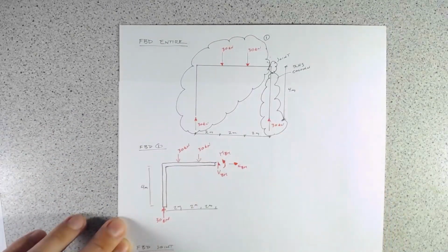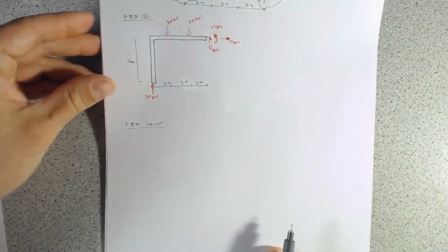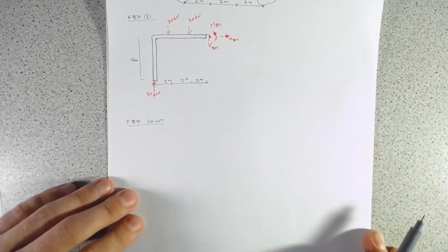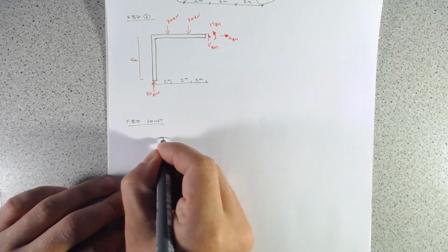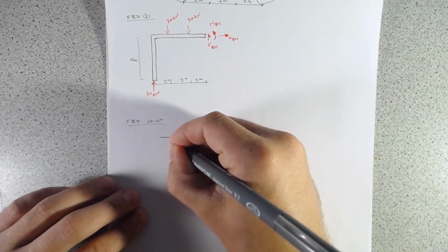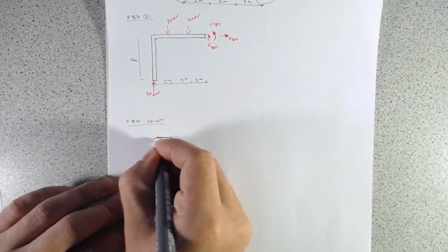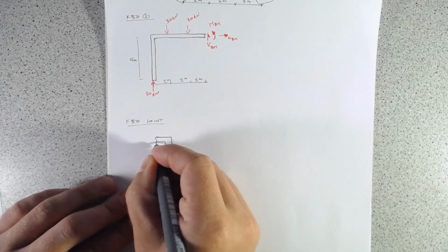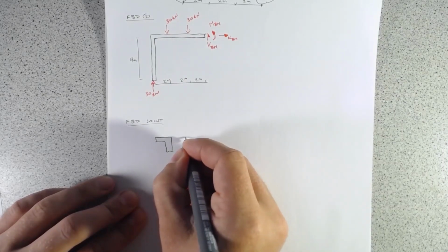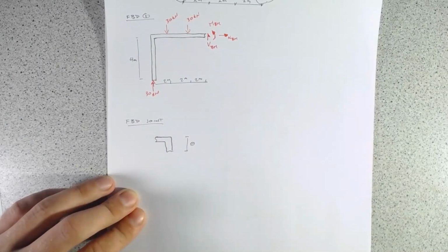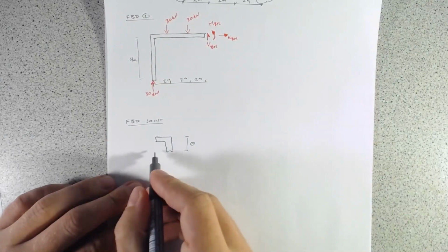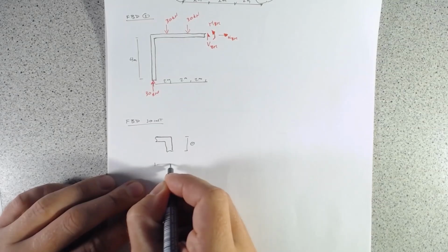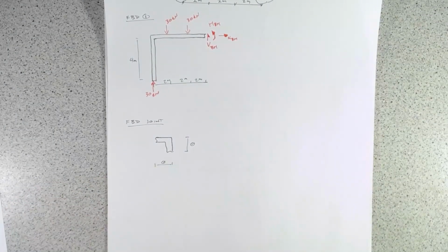So just this right up here. With the free body diagram of the joint, we'll draw it again with some thickness. And one of the things to keep in mind with this joint free body diagram is I'm going to assume where I've taken the cut is at an infinitesimally small distance, basically 0 away, and so that each of these arms is just 0 meters long. And the reason for that is it helps with the mathematics a bit.